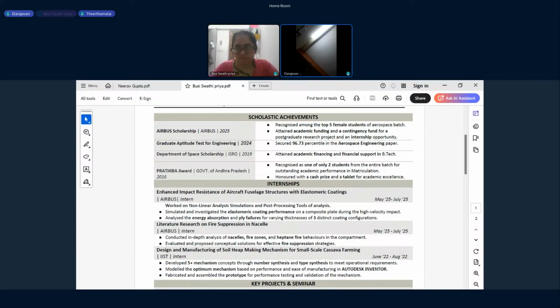Okay, and what is shock? Rise of pressure across a boundary is called shock. Not boundary, across the shock there will be a sudden jump in the properties. Yes, sir. So, what are the properties? Suppose you take total pressure. Total pressure after the shock, will it be reduced or increased? It will reduce, sir. Temperature, total temperature? Total temperature remains constant. Why?